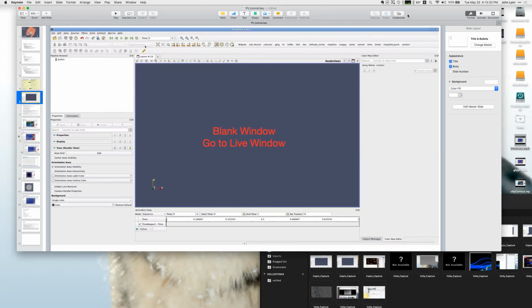Joe says, I've had trouble rotating 3D isosurfaces in Visit. No problem with Paraview. Is this a common issue with Visit if data files are big? I don't know. You have any idea, Kerry? If I recall, there's an option that's turned off by default to essentially have it not render while you're rotating, which is usually what makes it slow, that it's trying to render every step as you're moving the thing around. You could have it instead just rotate the wireframe around, and then it will re-render when you're done.